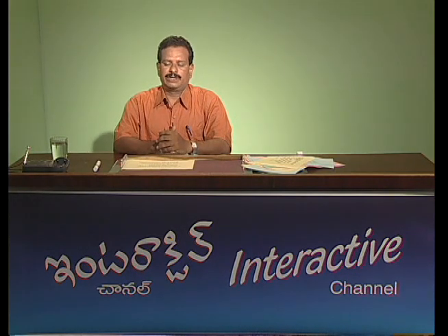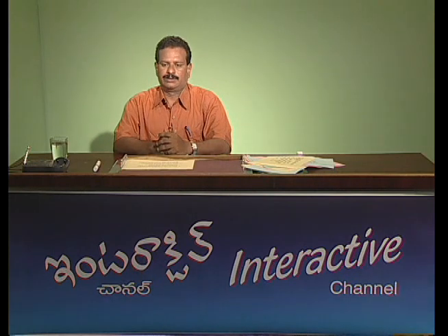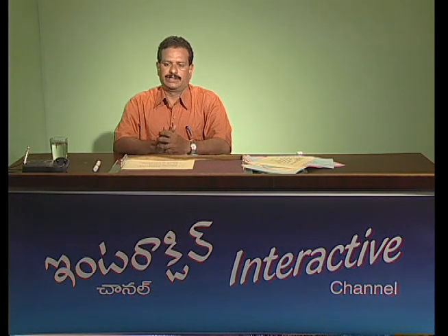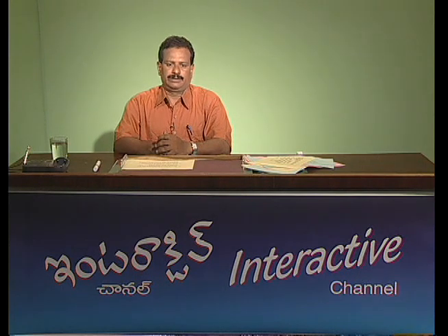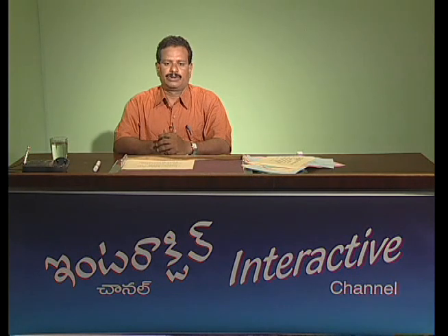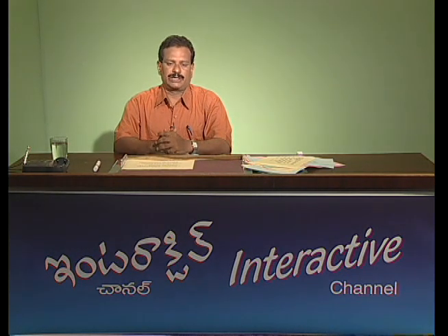Before designing good lighting, we have seen the factors to be considered, like utilization factor, absorption factor, reflection factor, waste light factor, etc. And for good illumination, we have derived the formula: illumination equals I by d square, where d is the distance between the object and the source, if the light is falling directly on a plane perpendicular to it.